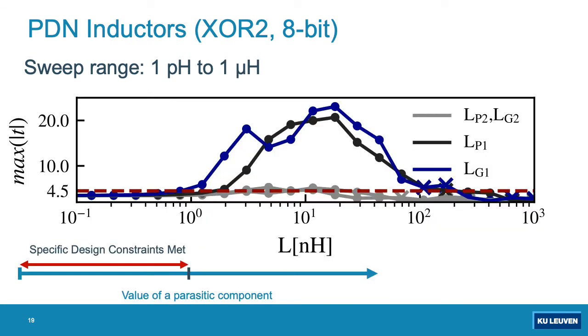And how relevant it is, we can discuss by looking at the values. Here we show the max-T score depending on the value of the parasitic inductors. X's denote the moments when the circuits start malfunctioning or stop operating properly. Now, these values are unrealistically large, especially if you assume that they stem from the logic core itself.